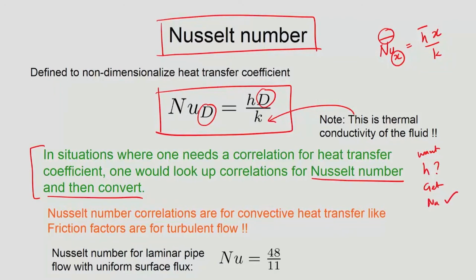And then use it as a boundary condition. So, it is very important in metallurgical scenario, you have situations where the fluid flow could be quite complex in various geometries, and we do not have to go ahead and solve fluid flow in all those situations. Very often the Nusselt number for those situations is already available as a correlation. So, we can use it and get the heat transfer coefficient, and then our problem will become just a conduction problem.